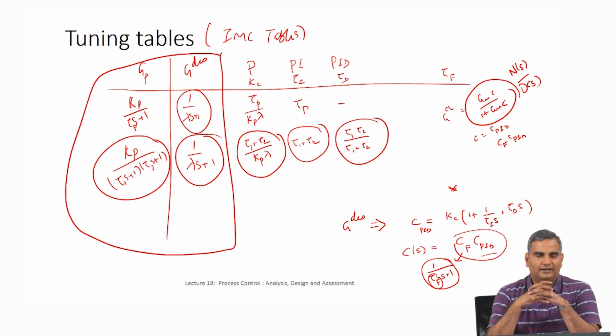So once we have that, then we said okay, you might get the output in the Laplace domain, but really ultimately for you to understand all of this you need to get the output in the time domain. So we said the process is you have a time profile for the input, you convert that to Laplace transform, multiply it by a process transfer function, get the output, and then you do the inverse Laplace transform.